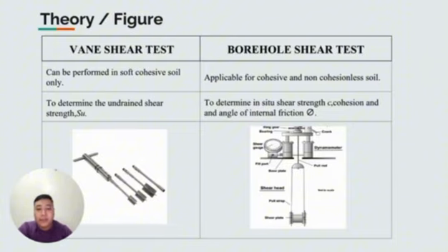On the other hand, the borehole shear test can be used for both cohesive and cohesionless soils. It is performed inside a borehole to determine in situ shear strength parameters, namely cohesion and angle of internal friction. These parameters are essential in soil stability and foundation design.